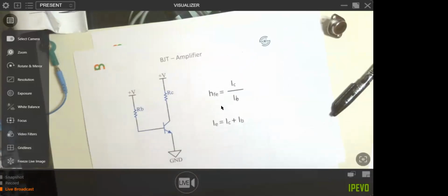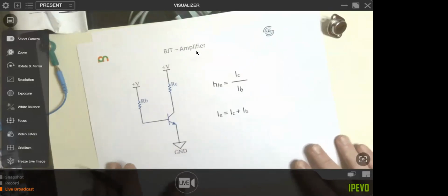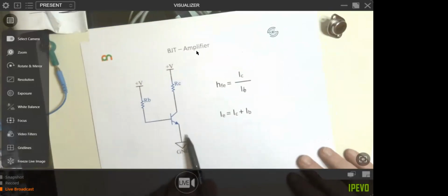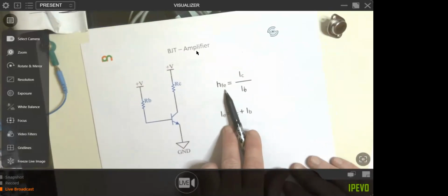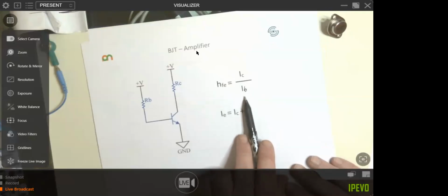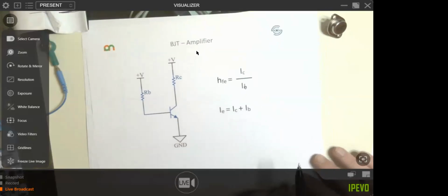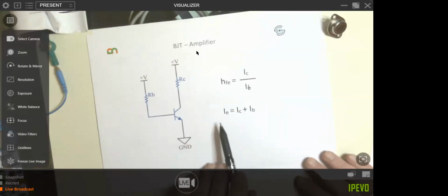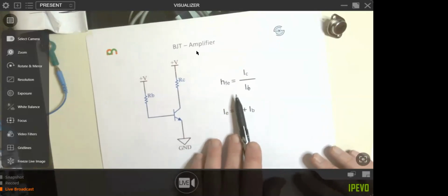So that's something else that you can do with transistors. I'll be honest, I've never worried about doing this, but it's certainly something you can do if you felt so inclined. Going back to the early transistor we spoke about, every transistor has an HFE, which is the ratio between the current through the collector and the current through the base. And if you remember, what I did say is every transistor has an HFE value, but it's never fixed.